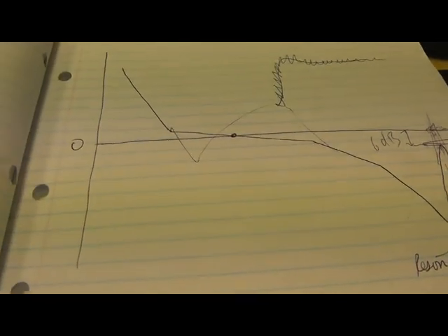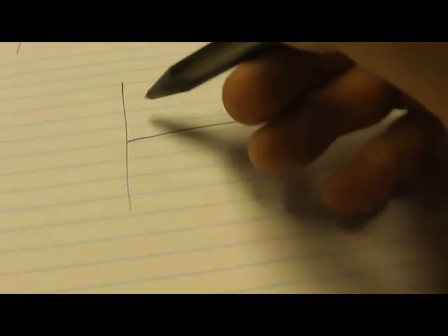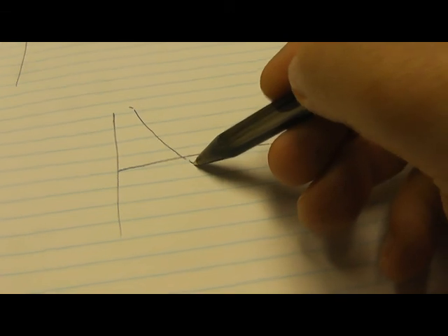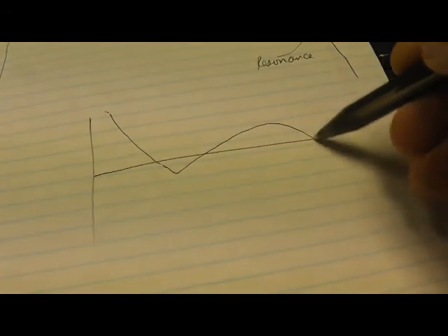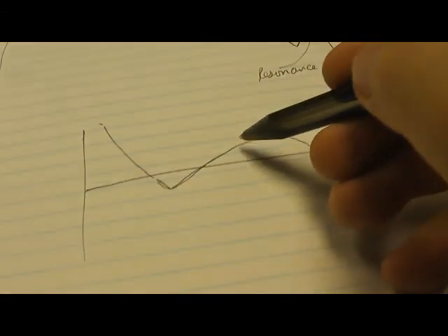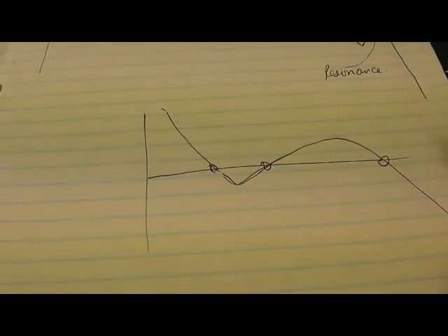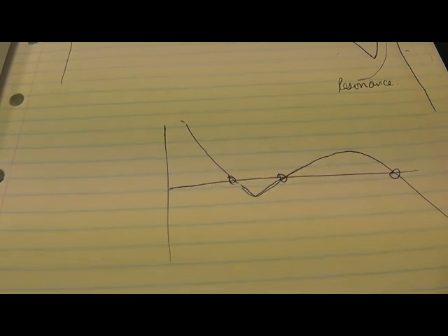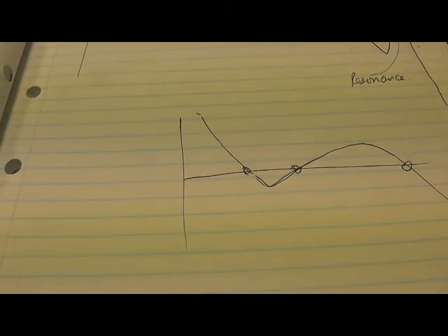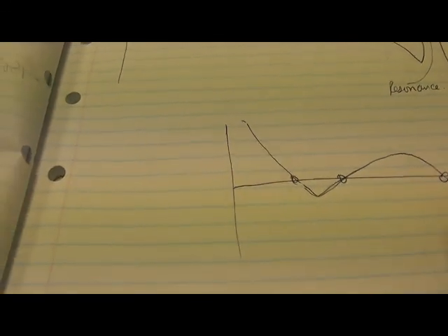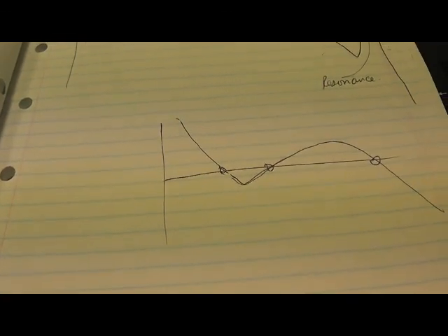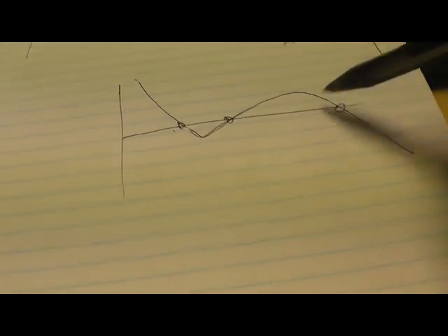If you did go through in a positive slope, some people want to know this, what would happen is it would go down like this, and then it would go up like that, and it would go down like that. It would be something like that. So you'd end up with 1, 2, 3 phase margins. And it's possible all 3 phase margins could be stable, but that doesn't really help you, because they've kind of got different speeds of responses.